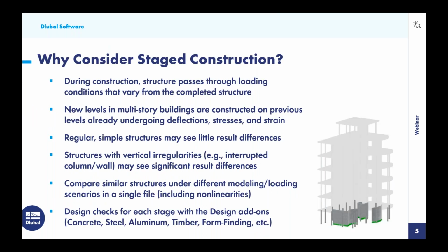So we might be wondering, why would we want to consider stage construction? Well, we know during the construction process that the structure may actually pass through several loading conditions that vary from the completed structure. So for example, when we're talking about multi-level story buildings and adding each additional level on top of each other, well, the previous level is already undergoing deflections and stresses.